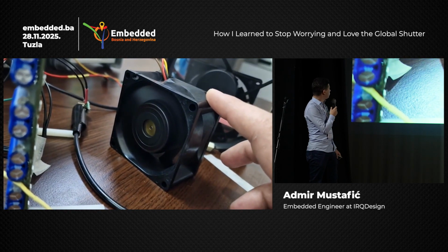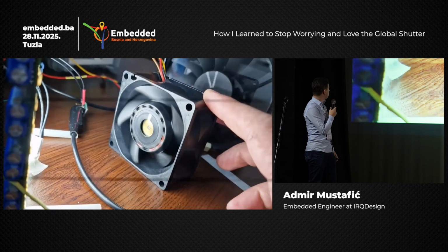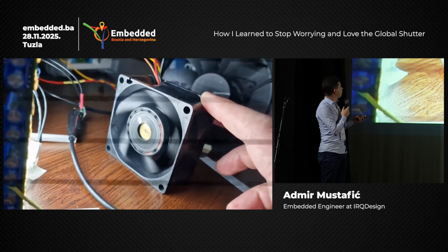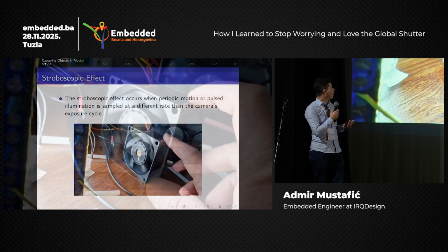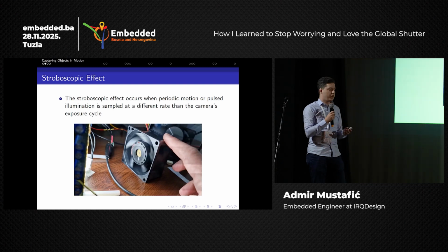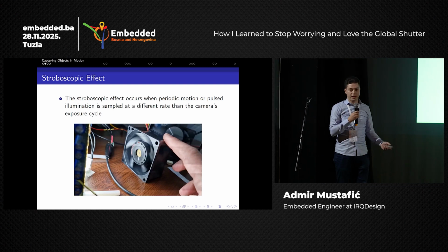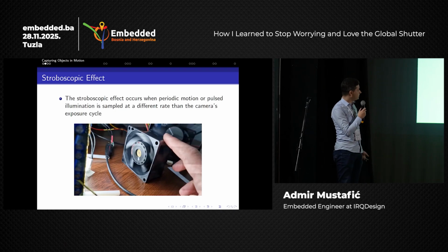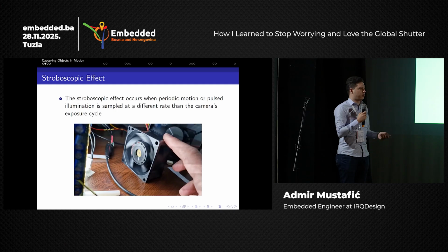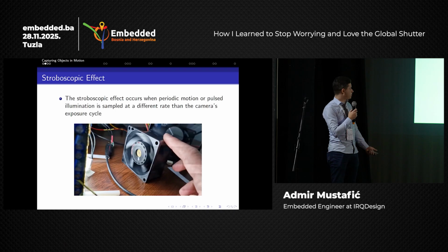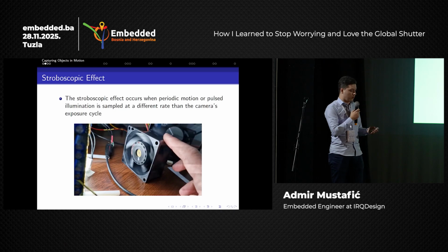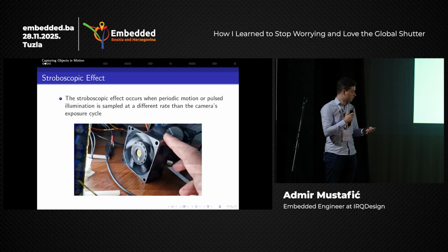And here, as we increase the frequency of the light pulses, we see the effect of the stroboscope, where we have the so-called wagon wheel effect. The rotation itself seems like it's off and moving backwards instead of its natural motion. And also we have the distorted image, so it is not valid for our automatic inspection control systems where precision is mandatory to inspect, for example, objects on a moving conveyor belt.